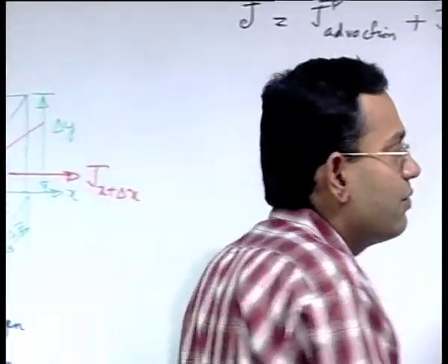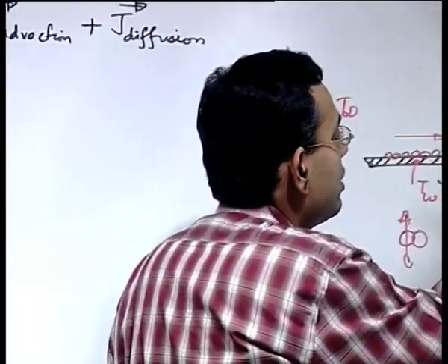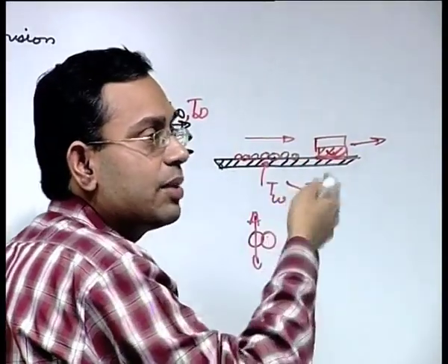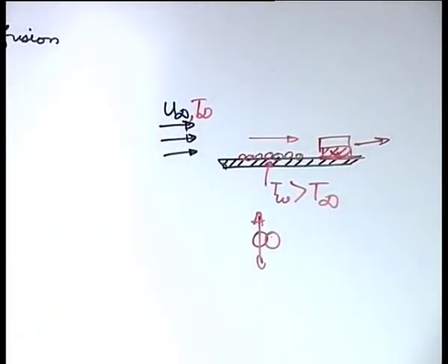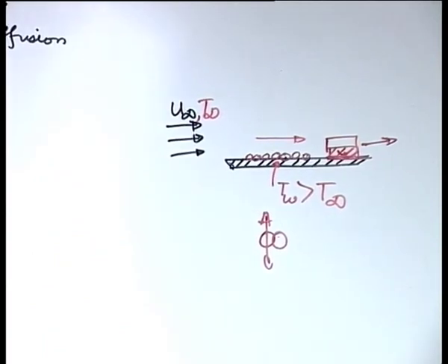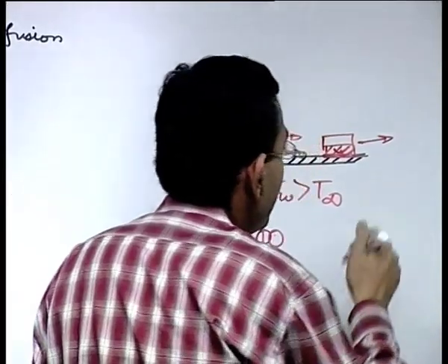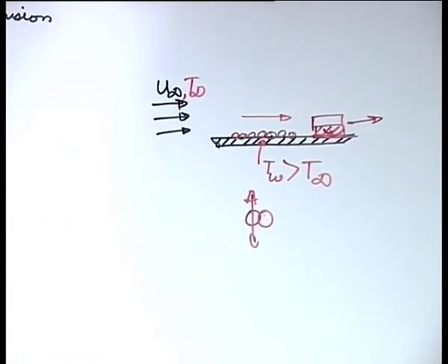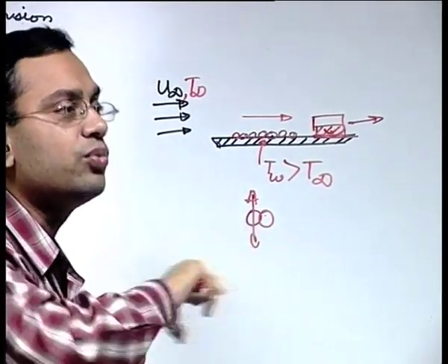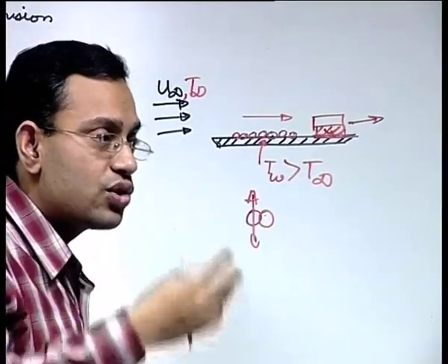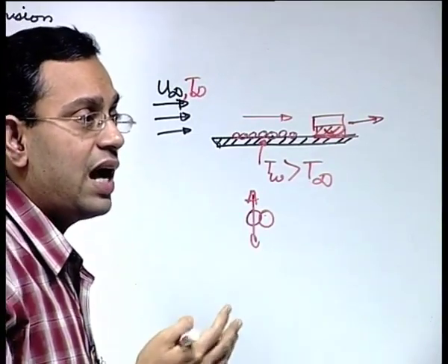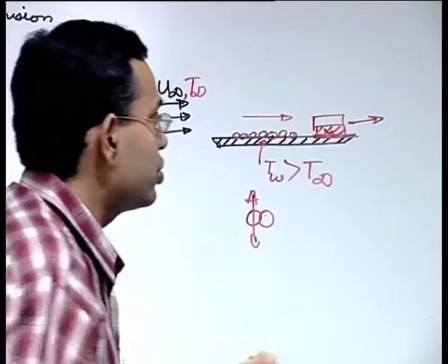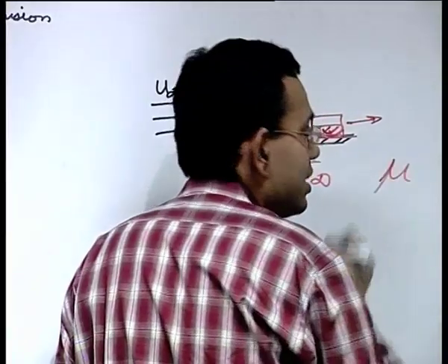So, you have a momentum disturbance that is being transported from the wall to the bulk fluid, and the viscosity is the property that does that. But is it the viscosity that is solely important? It is not so, because the fluid also has a tendency to retain its momentum. That is, if it is moving at a fast rate, it tends to move at a fast rate. If it is slow, it tends to move at a slow rate, and the momentum disturbance sort of changes this.